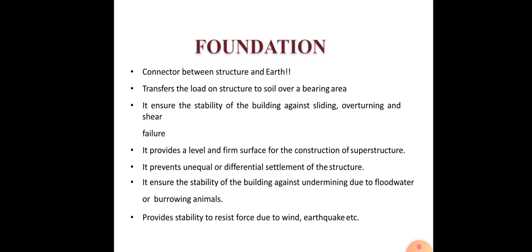And there are various functions for the foundation, like I told you. Most importantly, the function is that it distributes the total load which comes on the building uniformly to the soil, and also it provides a level and a firm surface for the construction of the superstructure. So once the construction of the foundation is completed, we know that it will form a level surface over which we can construct the superstructure.